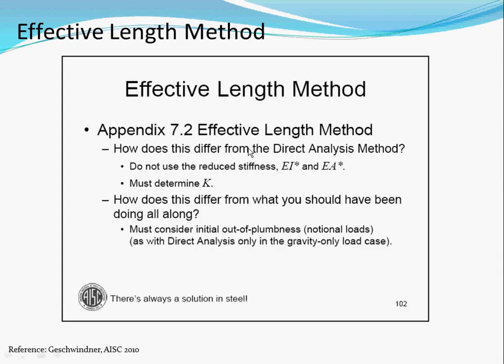Effective length. There's a second method. So how is it different from a direct analysis? Okay, this one we must determine the K when you're doing effective length. So you do not use the reduced stiffness, but you have to determine what K is.